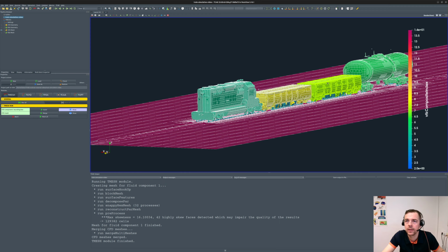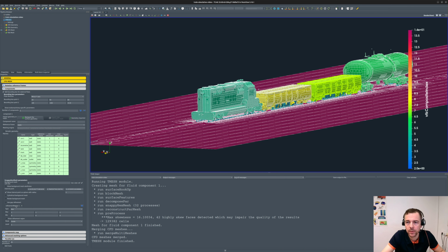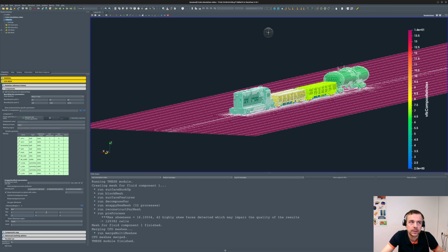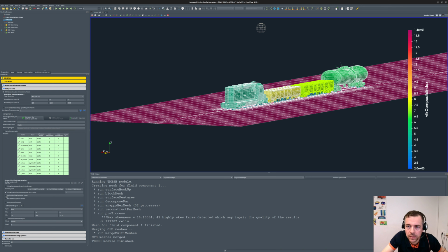Let's say we can add a refinement region, which is very simple. So let's add a refinement region. It will be a box around the model where there's even more refinement in the volumes, not on the surface, but in the volumes. This is important. I'll make it 3 meters to the left hand side, 3 meters to the right hand side around the model. And let's say 20 meters and minus 60, and let's make it 6 meters high and 0 something on the bottom.